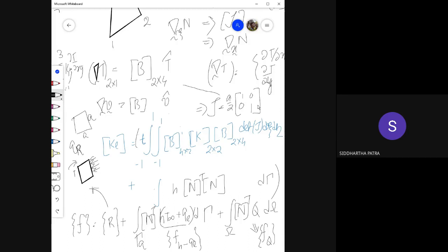So I know that the four-noded quad element is very difficult to integrate because there would be linear terms of xi and eta in the B matrix, even with a square-shaped element where the Jacobian is very simple. But since we are only working with a 3 by 3 or 2 by 2 matrix here, look at K here, it's a 2 by 2 matrix. I think you can do that integration. You don't have to use any numerical integration scheme or anything. Just simply do the integration.